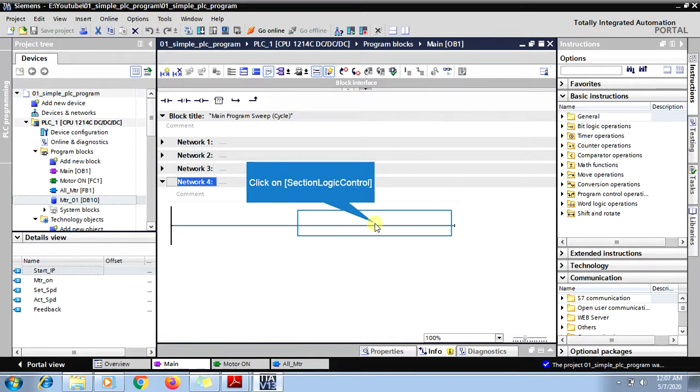As you all know, the analog input has its data stored in counts form, that is, it goes from 0 to 27648. So if I want to read data of say 0 to 100 degrees Celsius in the PLC, when 100 degrees Celsius arises, my analog input will read 27648, which is the maximum counts. If I don't want it scaled that way, I want something else, like half the counts, that is 13,000 something. So I can even do that.